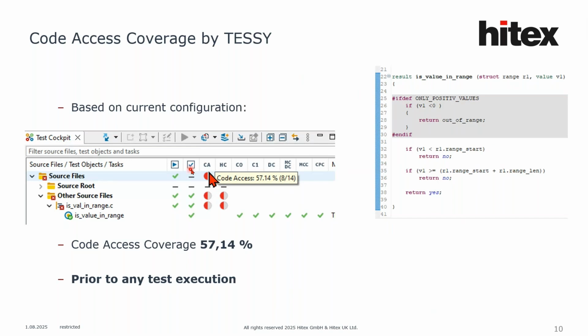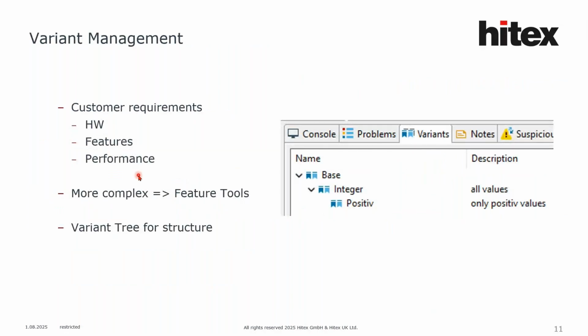Typically, the intention is to have a variant management. What does it mean? Typically you will not have one C file. You have a lot of C files, and if you have one part switched on or switched off, that's not the problem. But you might have more modifications, related not only to features, but also to hardware, different controllers, different interfaces. You might have other performance.